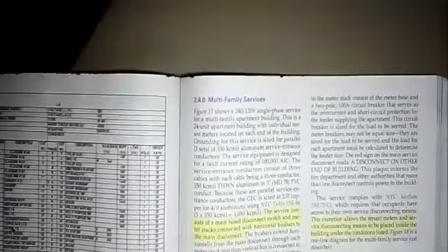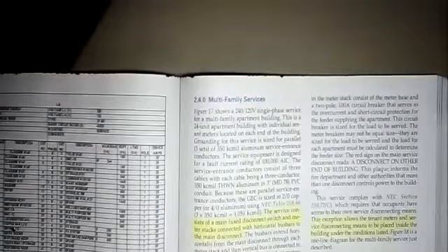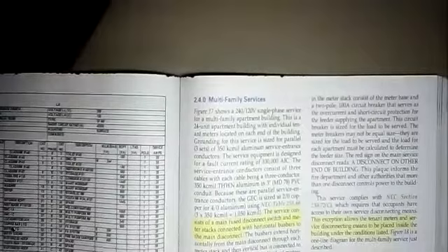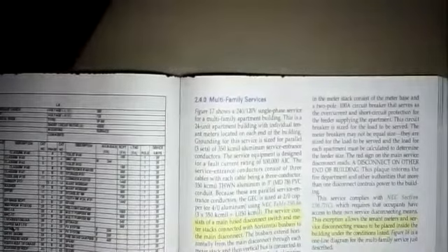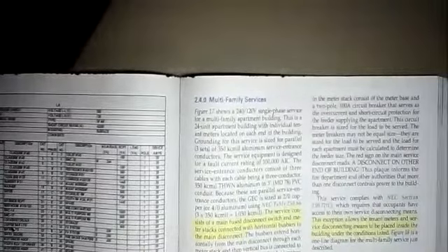The Y is a good secondary because it doesn't have a high leg. So in situations where you're going to have a lot of single phase loads, ungrounded to ground, you want to have the ability to have an equal distribution of power even on the B leg, B phase. So you want to have Y so that you don't have a high leg.